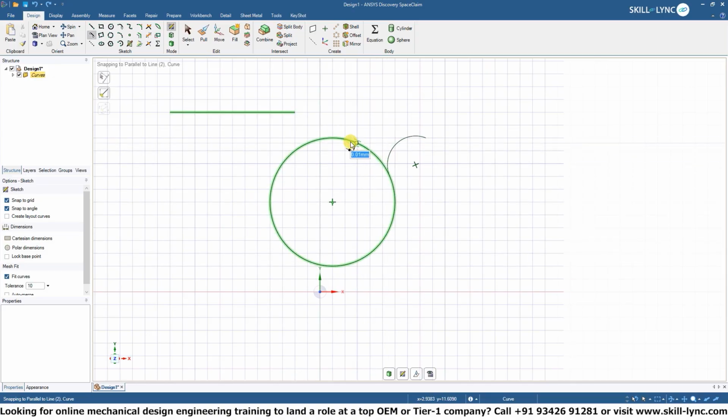See how I click the circle, I click the curve, and then you can draw a line, but it remains connected with the circular curve. It's another thing that you can use. Obviously, you can change the angle. You can set it at 170 degrees from the horizontal. Just different things, different modeling tools that you can use.